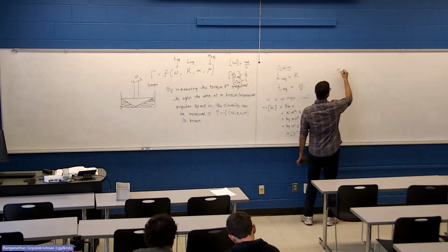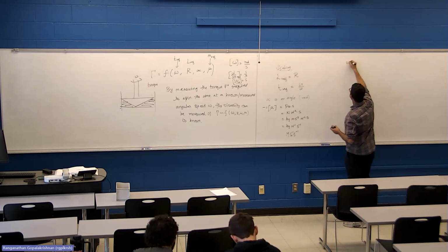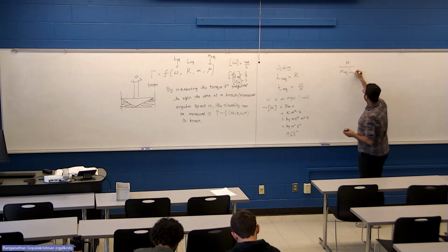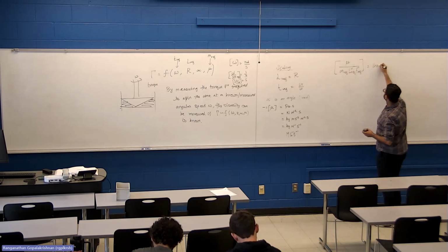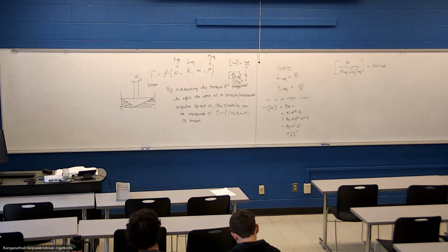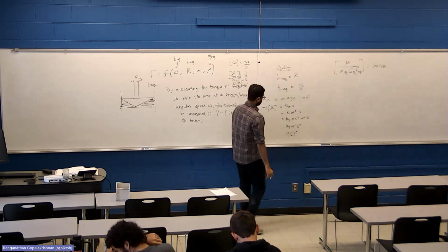Viscosity divided by M reference times L reference to the power minus 1 and T reference to the power minus 1, this quantity has to be unitless.